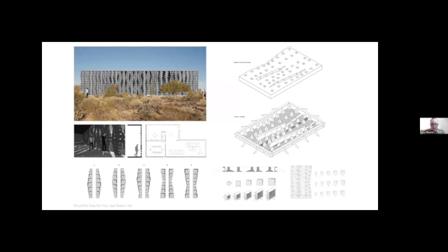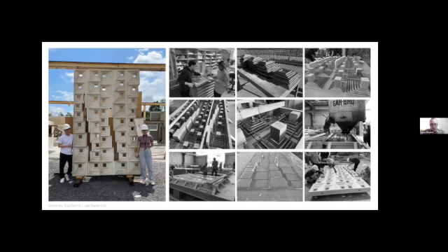Another example, again, usually a combination of digital with analog fabrication, and this is another example of the student work. So we talk about panel thickness, where the reinforcing should go, color, aggregates, also how you need an angle on the formwork, on the pieces, to make sure they come out. So all that is part of the learning process. So the students really get into the precast nuances to make sure they can have a successful outcome, but also learn about what precast is about.